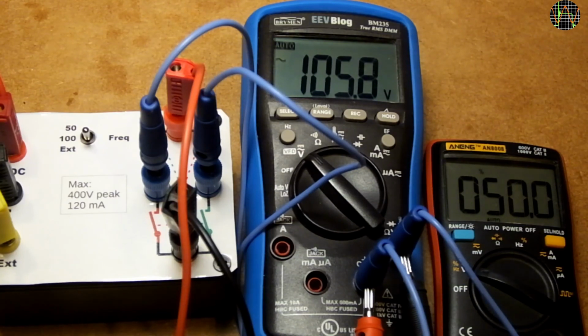You see, it all started when I noticed that the RMS voltage produced by my AC converter, which will be one of my next videos, was rather sensitive to the duty cycle of the square wave, but it shouldn't be, because the theory says that the RMS of this waveform doesn't depend on duty cycle. The blue meter is showing the AC RMS voltage and the red one the duty cycle. You can see that the voltage drops as the duty cycle changes. It turns out my AC converter had nothing to do with this, it's rather a feature of the multimeters.